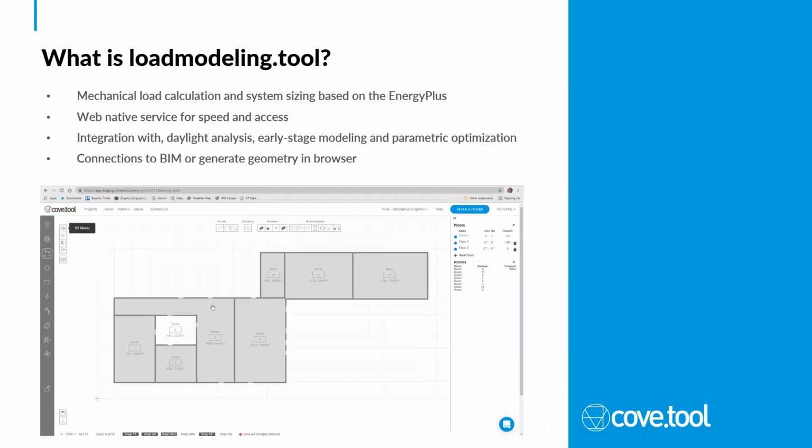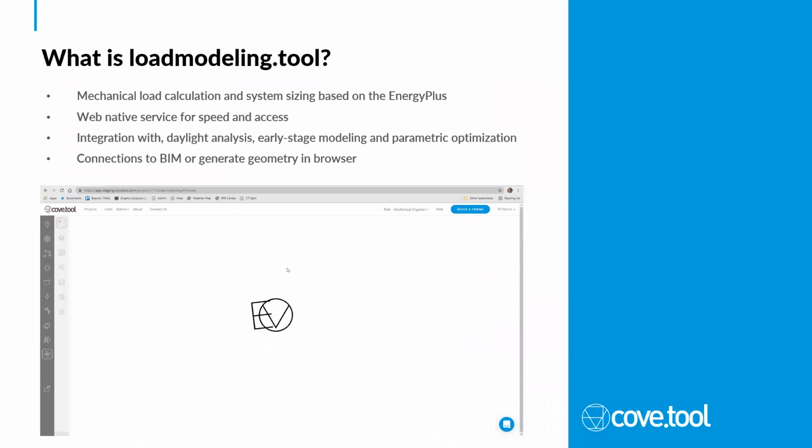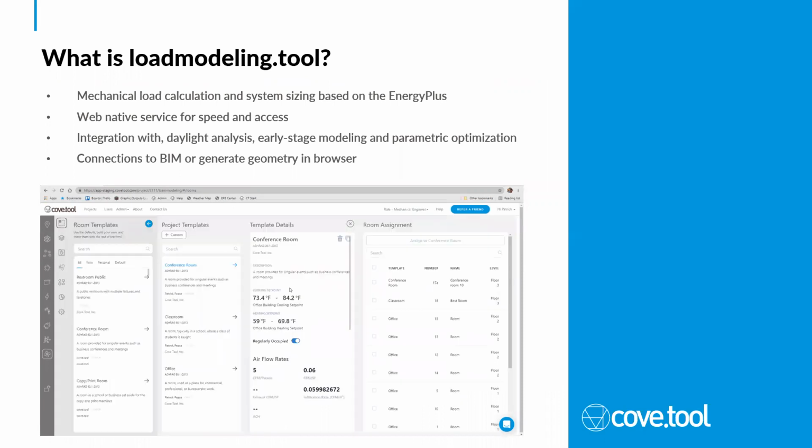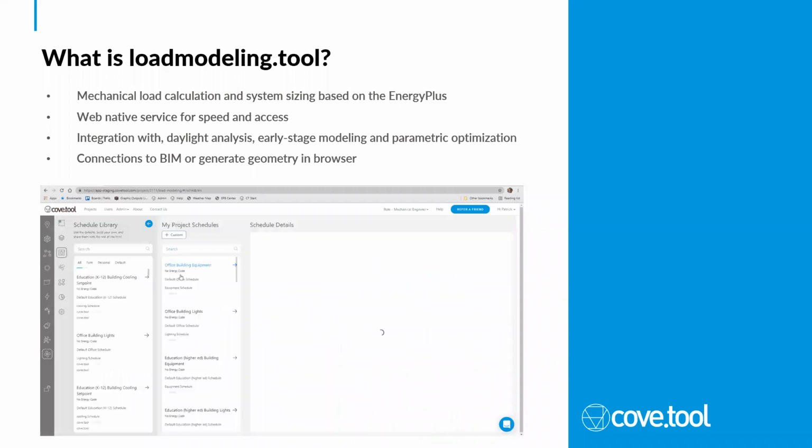And so right off the bat, what is loadmodeling.tool? It's exactly in the name. It's a mechanical load calculation and system sizing tool, and it's based on the EnergyPlus simulation engine. So all the calculations that we're doing go through EnergyPlus. That's the engine we're using. It is a web